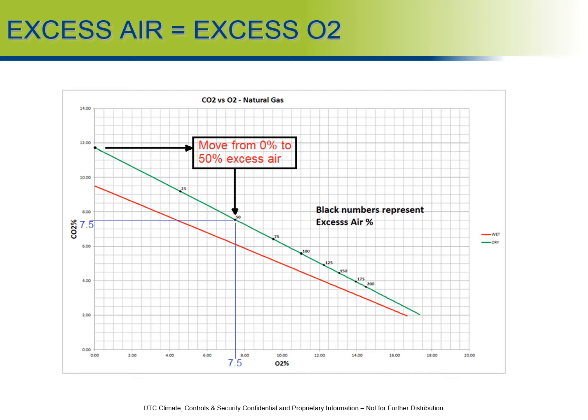For proper combustion, you're typically going to see that CO2 and oxygen level range between 6 and 8%. Naturally, split 50-50, 7.5 to 7.5 would be a perfect scenario. But you're going to have some ranges between 6% and 8% based on the CO2 to O2 relationship.